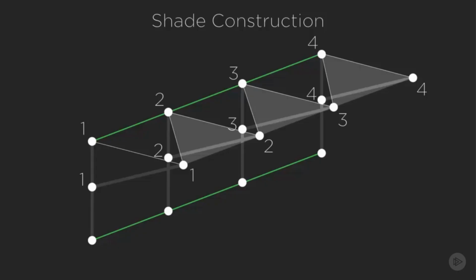The challenge of this section of our exercise is that we have to connect a surface from an isolated mast and boom arm to a point on an adjacent boom arm. The method that I've chosen in the Dynamo environment to represent the surface is a surface created by a loft.